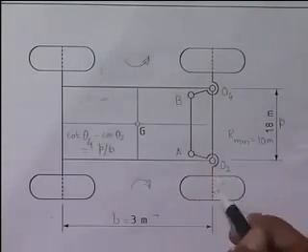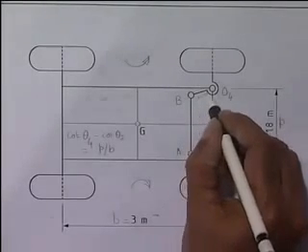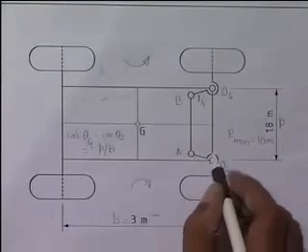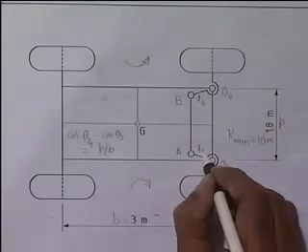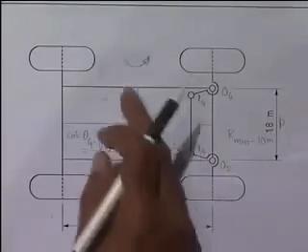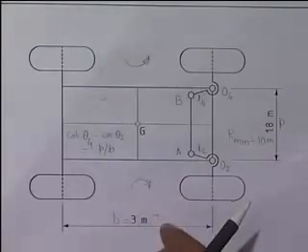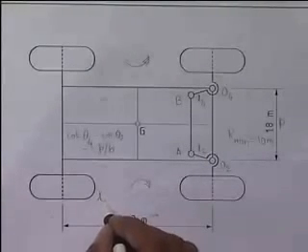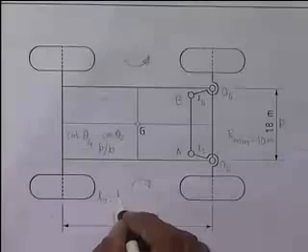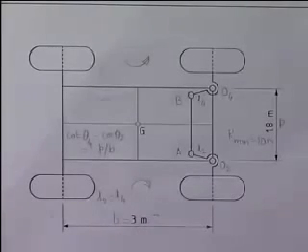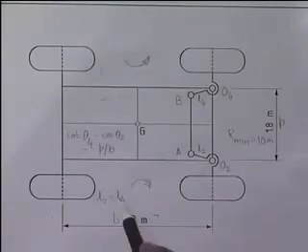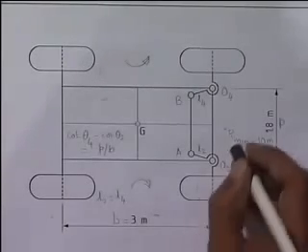However, in this case we must have a symmetric linkage, that means this O4B, the link length L4, and O2A, the link length L2 must be same to maintain the symmetry, that is identical turns for the clockwise or counterclockwise. So L2 is same as L4. Because this has to be satisfied, we do not have a choice. Obviously, we cannot even go for 3-point synthesis. We can go only for a 2-point synthesis.